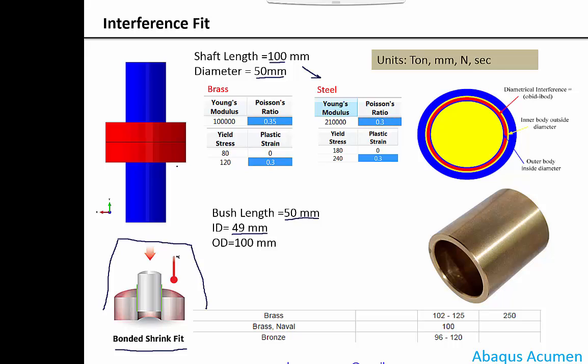Now as soon as you see this problem, you can immediately see we can do it using axisymmetry. So straight away it's an axisymmetry problem. If I take an axis along this, you can model this as an axisymmetric problem. So you don't have to do a full solid 3D element, where your computational time is high, and you have to deal with boundary conditions, stability and convergence issues. So quickly we can do it axisymmetric.